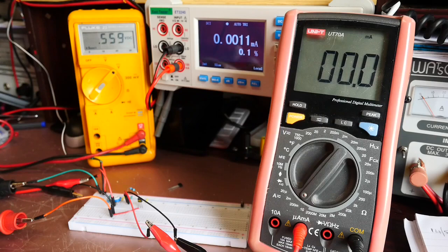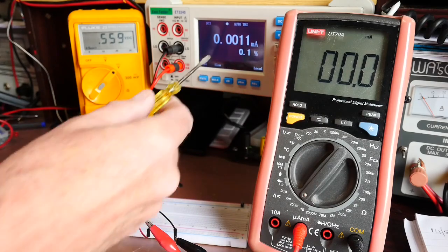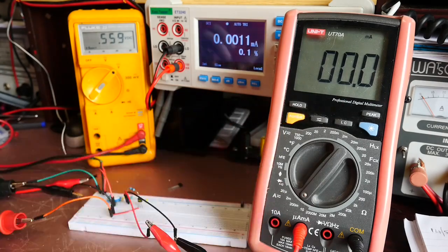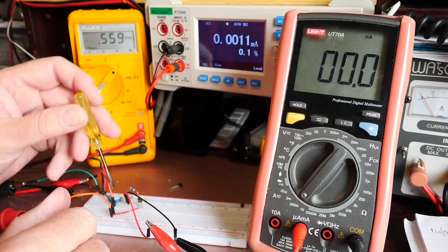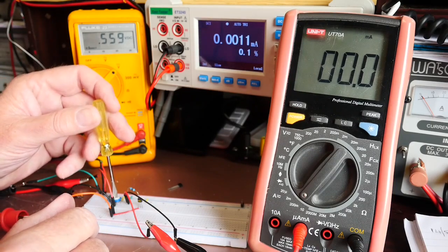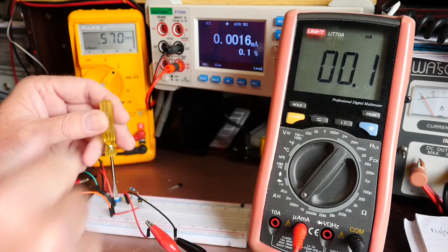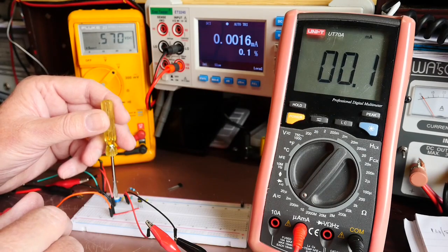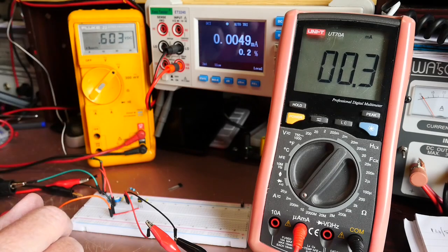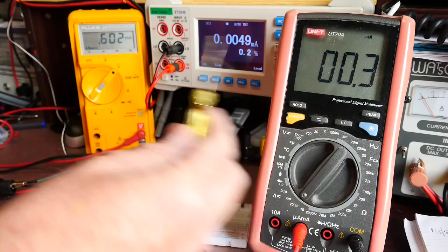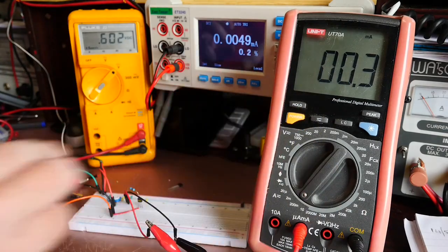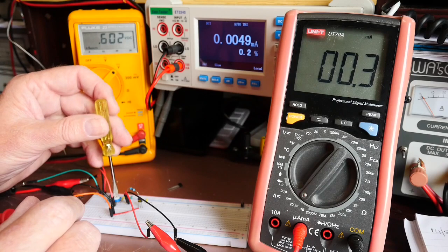Right, there's, well, 0.56 let's say, and collector current's increased slightly, but still no measurable collector current. But then as we approach 0.57, suddenly we start to see some collector current, and by the time we reach 0.6 volts we've got a little bit more base current, and we've definitely got some collector current now.